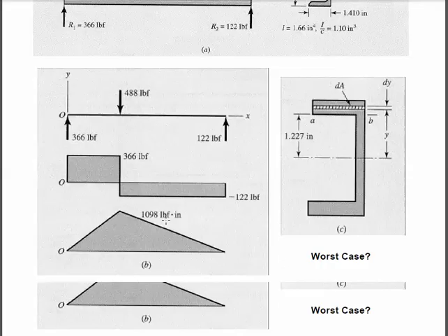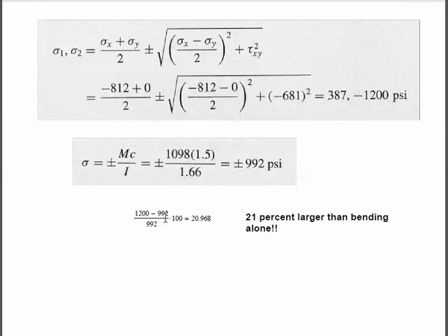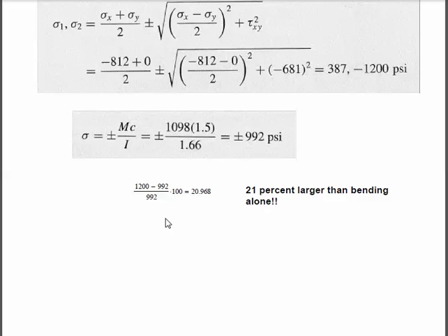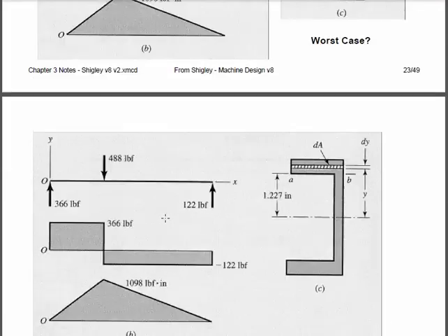And we'll see an example in just a second. Let me find it. See if I'm finding what I'm looking for. Maybe I drew a picture for you. Okay, this integral of y dA, let's talk about it on this picture. Let's say I want to know the Q value here, and I want to know the shear stress here. I draw a horizontal line on the axis where I want to know that shear stress. Then I look at the area above it.